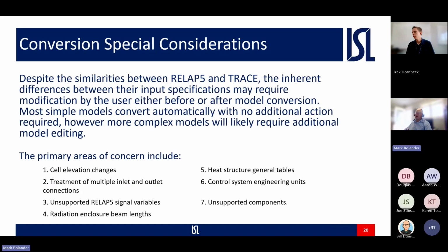Let's look at some conversion special considerations. Despite the similarities between RELAP and TRACE, there are inherent differences between their input specifications that may require some modification by you, either before or after the model conversion. Most simple models, like we've seen in the last 2 exercises, are converted over automatically without any additional action required. However, as you get into your more complex models, you'll more than likely see